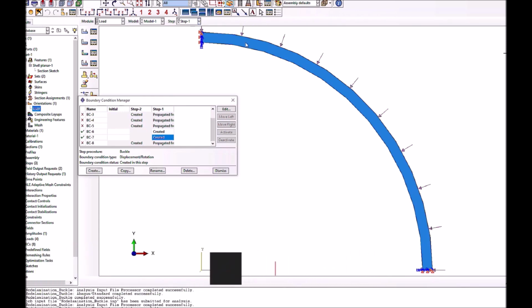And even now, we don't have any additional support. If it's a 3D structure and it's connected to those titanium rings at the end, then obviously you will get some resistance there. And also in the thickness direction, you will have some material, so you will have resistance there as well. So this is more idealistic. This is uncertain in my opinion, and I could have used, at these 2 points where I am prescribing u1 and u2 to be 0, a multi-point constraint and have a restricted motion here based on what is happening on the other side and along the thickness or longitudinal direction. So this is one uncertainty in the solution, and that's why I said these numbers are not 100% accurate, but they will give you a qualitative trend.